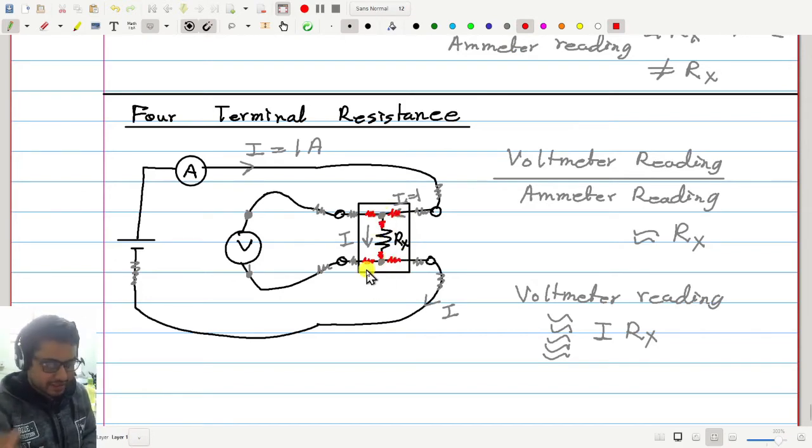And sir, how are we measuring the exact? Means there will be some. But that is not a problem, because these red resistances are fixed. Therefore this red resistance which I am pointing now, you can think we are actually measuring this red plus this Rx plus this, and these 3 things together I am calling Rx.